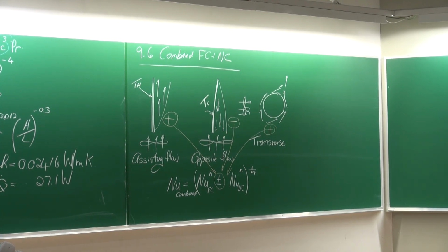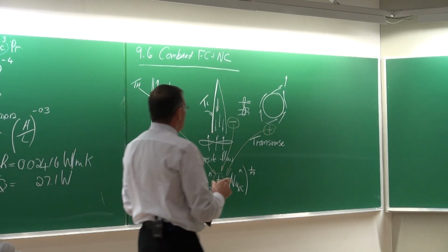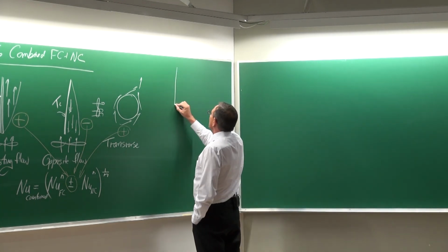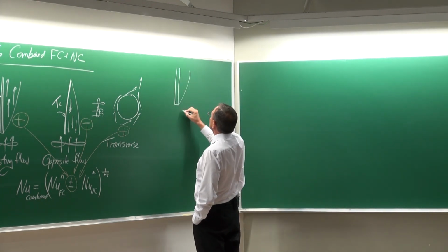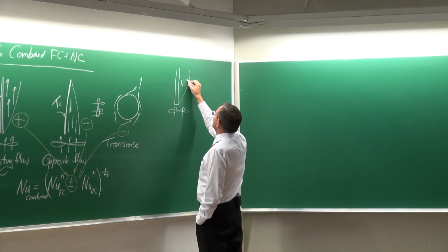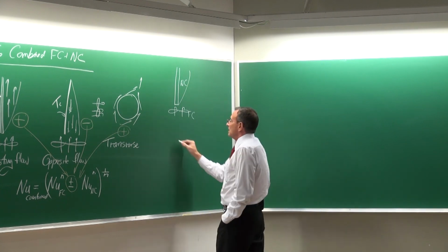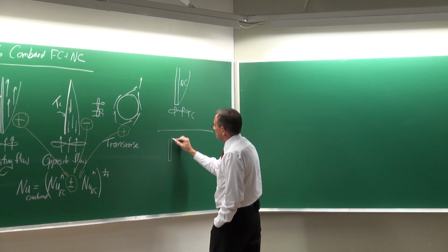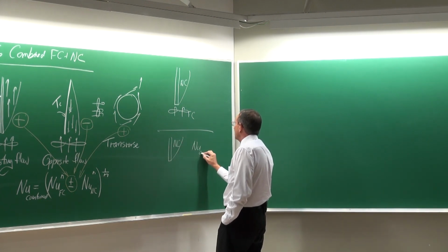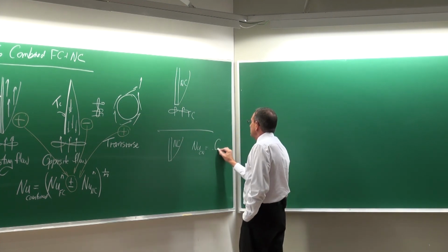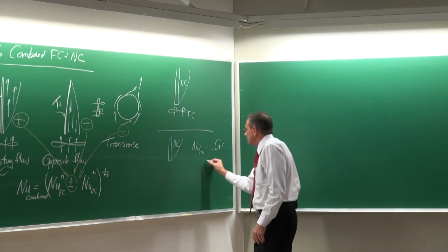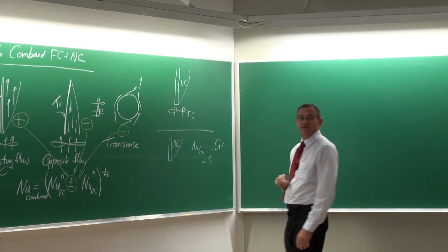Okay. So just to repeat, let's suppose you get a problem like this in the exam or the test. Here's the fan, forced convection, and there's natural convection. Then you're first going to look at the plate and you're going to get the natural convection Nusselt number first. And it's going to be a function of Grashof number, etc. So you're going to calculate it. Let's suppose it is equal to 5, which would be a very high value.